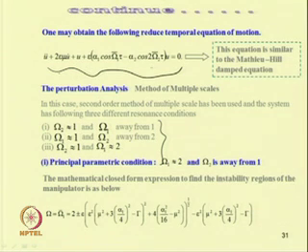So, we cannot apply the superposition rule in this system by taking this equation as equivalent to u double dot plus 2 epsilon mu u dot plus u plus epsilon alpha 1 cos omega 1 tau into u as one system, and u double dot plus 2 epsilon mu u dot plus u plus or minus epsilon alpha 2 cos 2 omega 2 bar tau into u as the second system. As the superposition rule is not applicable, we cannot take this as two Mathieu equations and solve them.